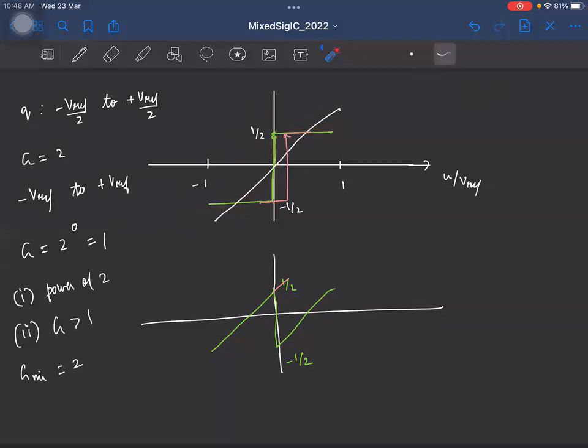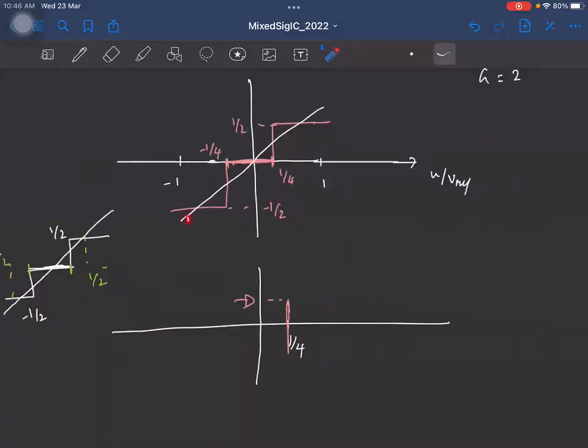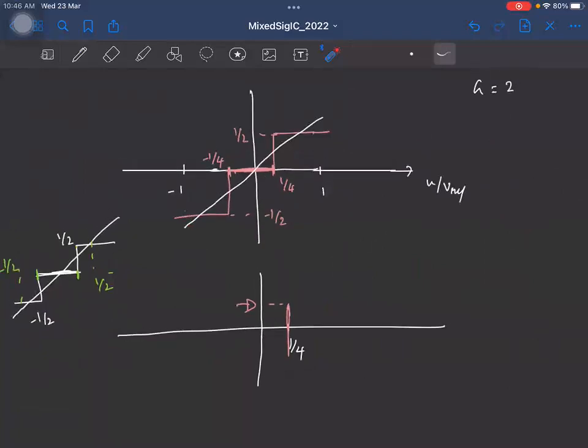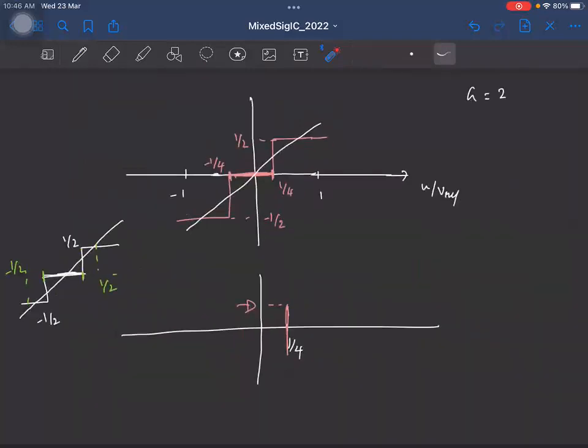Okay, with the expectation that this might be suitable for choosing a gain of 2. Correct. Yes, effectively it's not now a 1-bit ADC. Let me come to that. Since I have 3 levels now, this is no longer a 1-bit ADC, right? To represent 3 levels, you need at least 2 bits. Okay, let's come to that. So let's go to that later.